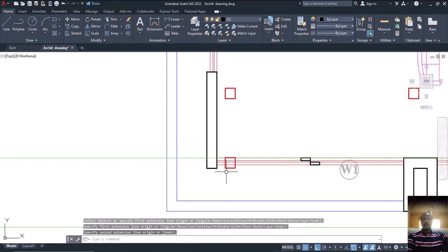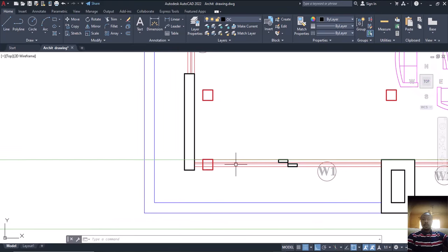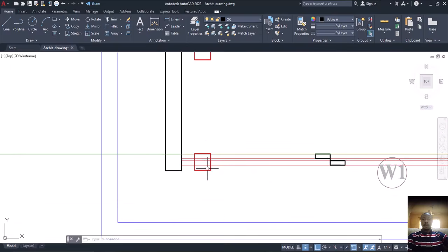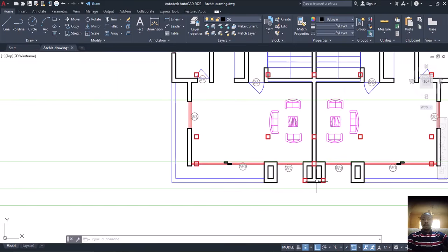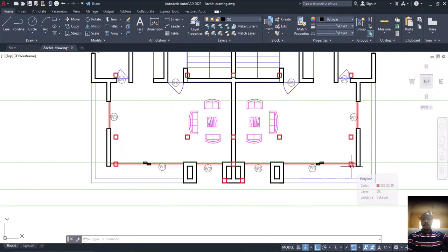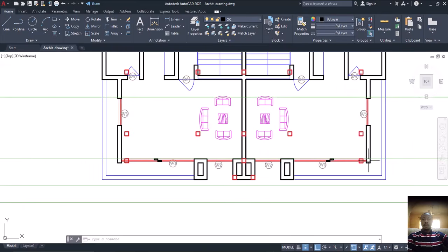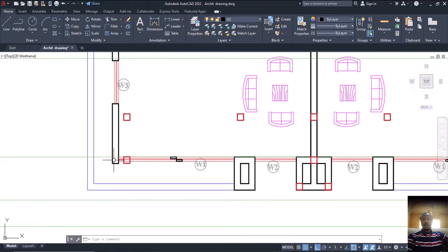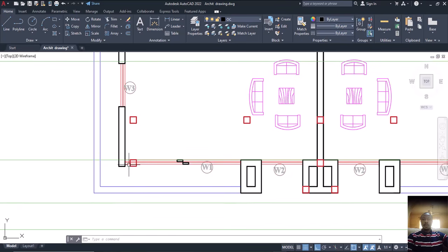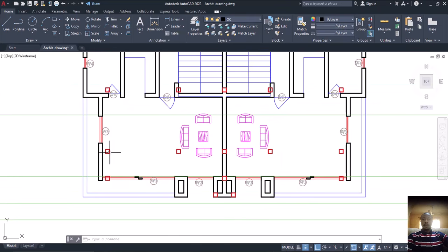So what I'll do is that I'll remain this column where it is. Is that okay? Whatever they want to do from here to here is okay for them. So I'm going to leave this particular column. This column will remain, and this column will remain. I will not shift this one because of this small space. Because if I shift this one here, understand, it might give me much more load, which may make this column to be robust, big. So that is that. All right.